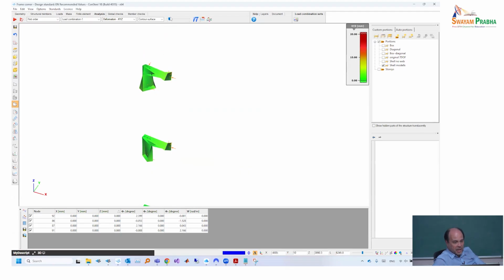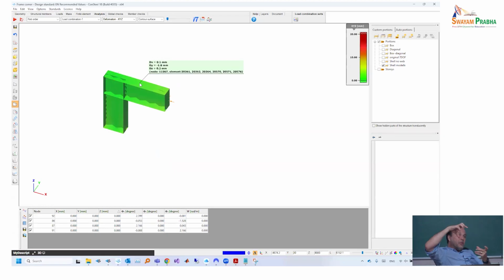That's clearly coming from how the warping deformations, which are just flange bendings, are not necessarily the same. So the flanges may bend in the opposite direction. That's called warping. And really the question is how that information goes through the connection, what will happen, and how we go down.